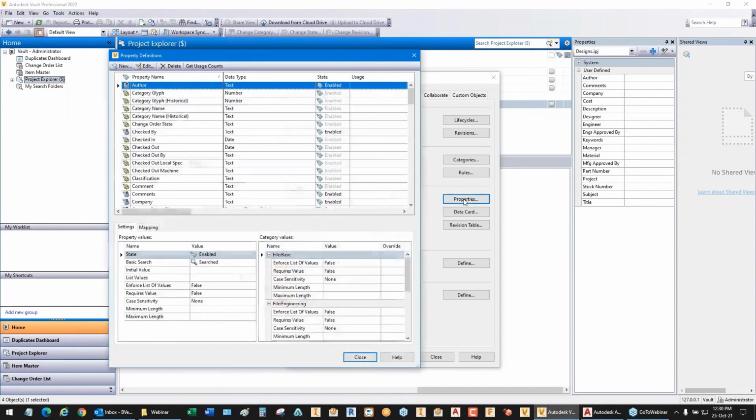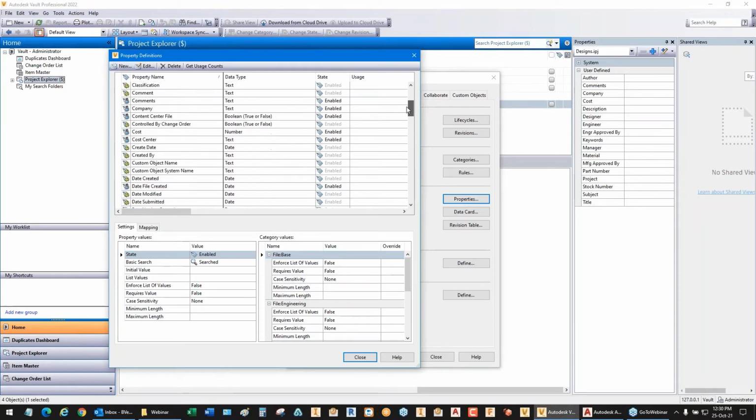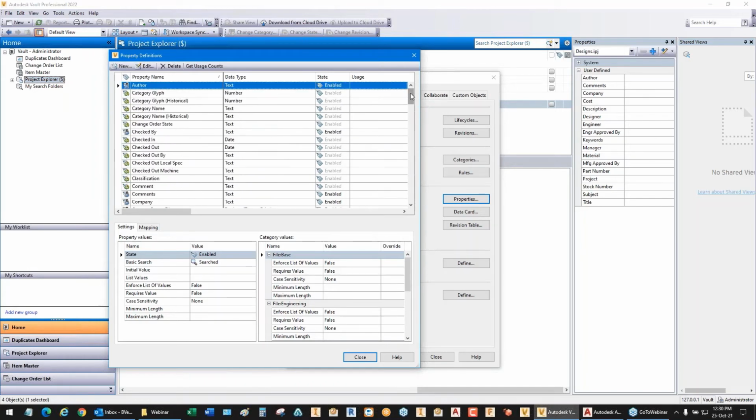This displays the properties that the Vault either has built into it natively to interact with a lot of the CAD tools that are out there, including AutoCAD, AutoCAD Electrical and Inventor. Looking into the properties section, we see a fairly significant list of existing properties in use by the system, and that allows us to do searching. One of the things that's not here is the property for the vendor. So I'm going to provision or add that here so that it will be managed and manageable by the CAD system or by the client Vault system.